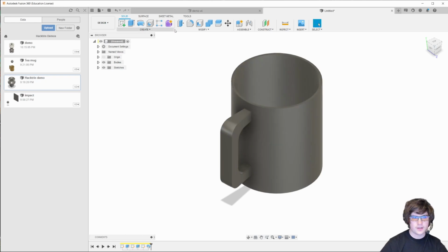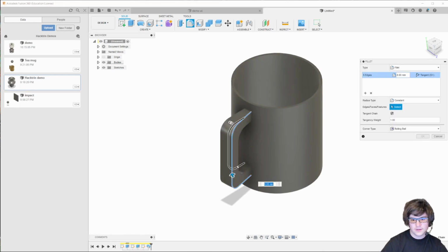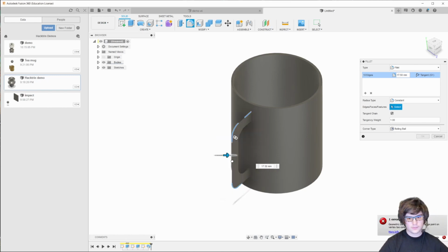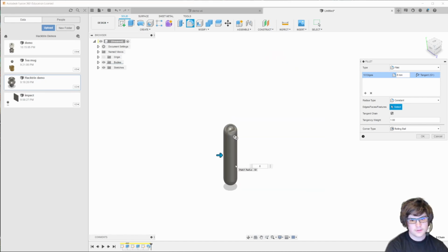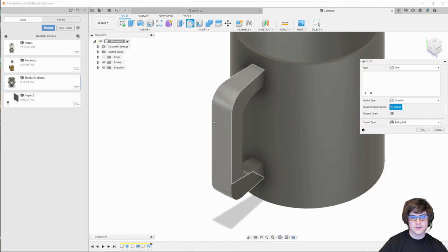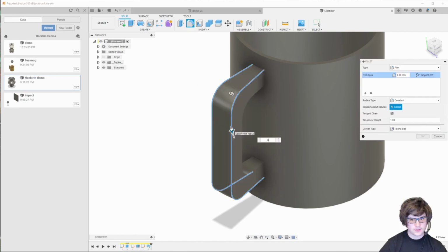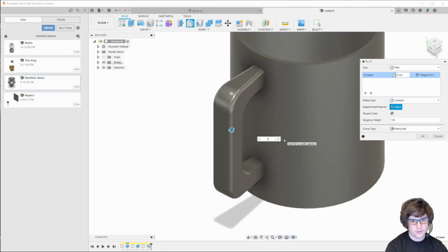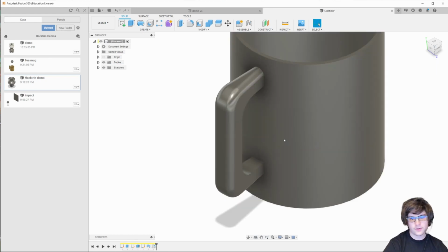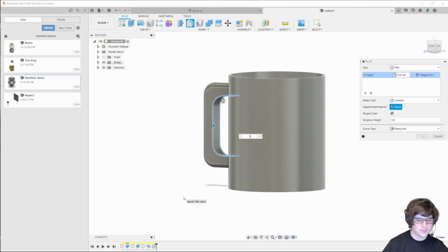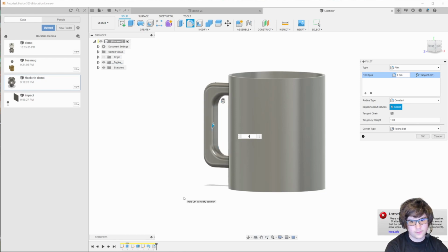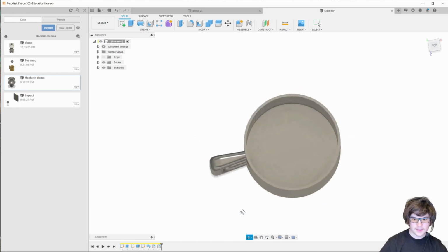And then it still has some sharp edges, so let's add some fillets. It's a bit much. That is interesting. Let's try that again. 6 millimeter. Nope. 3, 4. Sometimes with fillets you have to experiment. Like it might glitch out a bit. Just try changing the numbers to something smaller. Okay, let's make these also 4 millimeters. And now we have a nice handle.